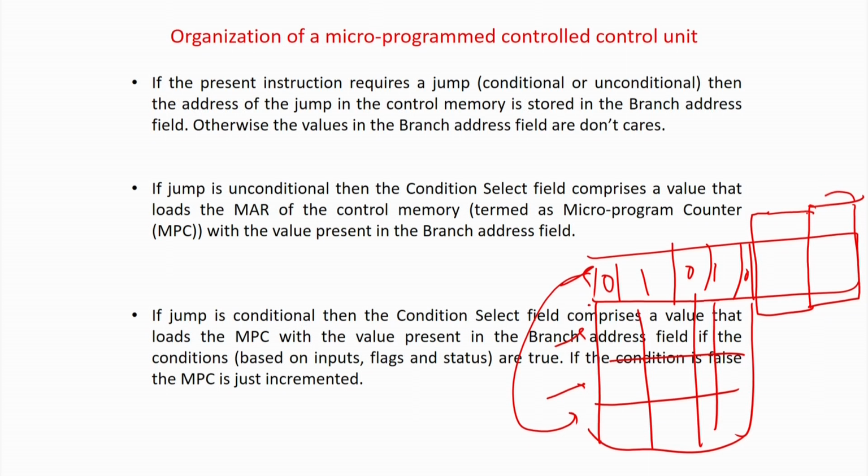So some part of the memory here will tell what the next phase is, that is, the address. That is the address of the next location which the microprogram has to go to, if some condition is satisfied. Another part you have to keep for some conditional variables, maybe the variables which have to be checked. I am just telling you the basic gist. In a few slides we will see more concretely how this is to be designed.